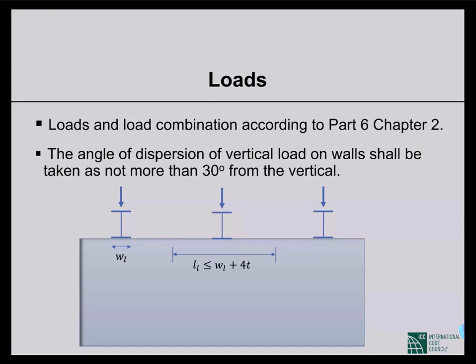So this is limited to this value. We can divide the load by the loaded length and the thickness of the wall, then we can get the stress in a simple way.